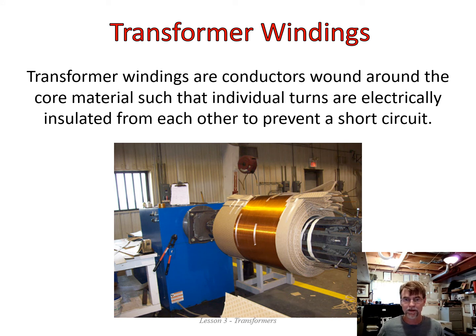If you follow the current, it would come in and short circuit across all of those wires that are touching and exit the other end of the coil of wire. So it's absolutely necessary that there is insulation there, no short circuits, so the current must travel through the entire coil, because it's that coil that gives us our inductance. So even though it doesn't look like it's insulated very often, it absolutely must be.